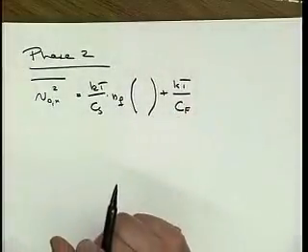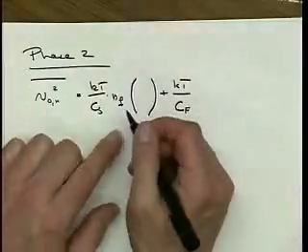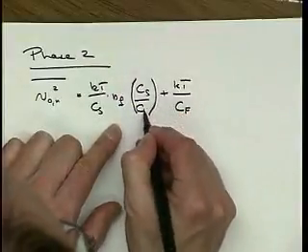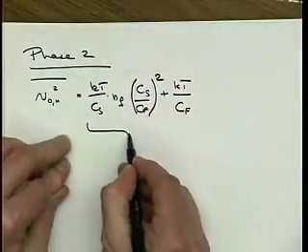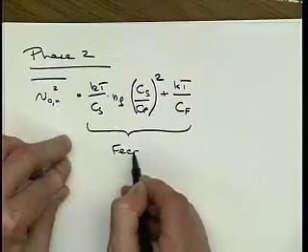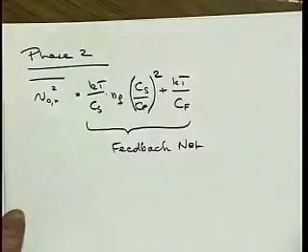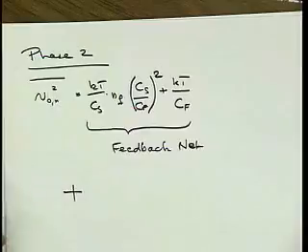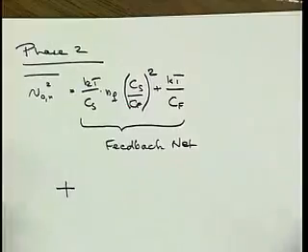It is amplified by the exact same gain as the input signal, as all the other charge that we've stored onto CS. And again, don't forget the square. Okay, so that's the feedback network. So that's our first noise. Now we use the fact that we have linear superposition.